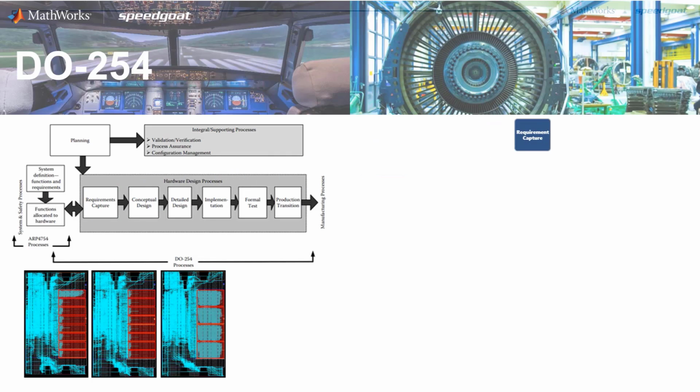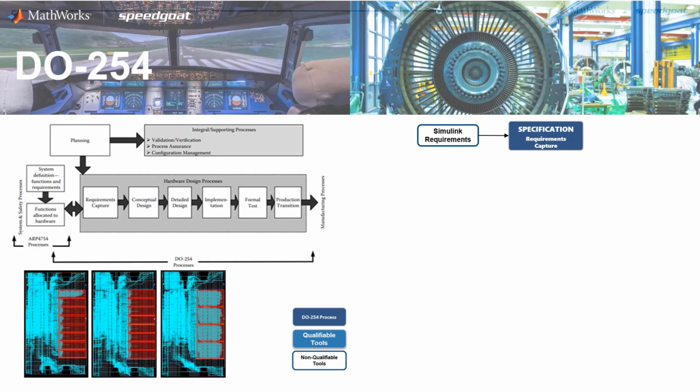These requirements can be then specified using Simulink Requirements. These requirements can also be linked to other requirement management tools. Then the conceptual design will be mapped to a Simulink model. Of course, Simulink can be mixed with other toolboxes, Stateflow, etc. And it will be especially interesting in this case to play with the automatic conversion to fixed point.